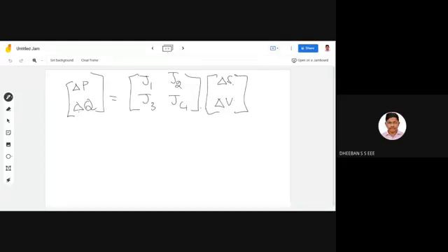And now, as per the decoupling methodology and your sparsity feature. From the sparsity, your diagonal elements will be of larger value when compared to that of your off diagonal elements. So these two values you can just neglect. J2 and J3 you can just consider to be negligible.